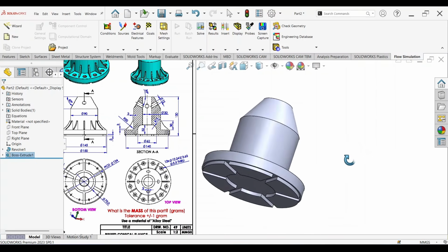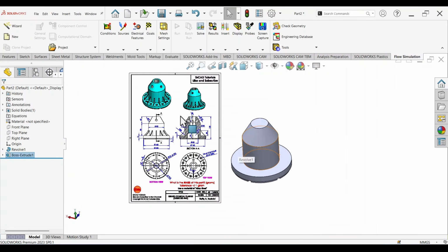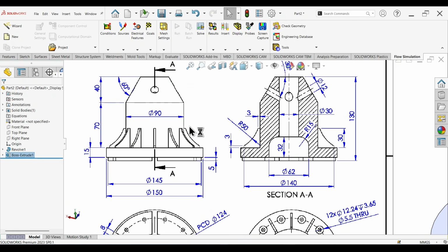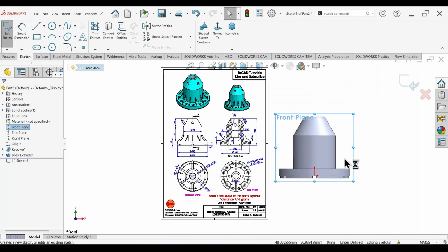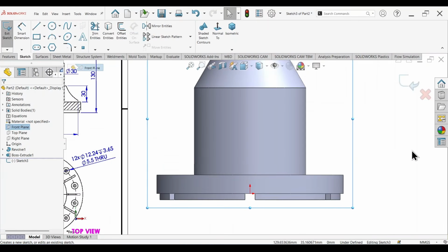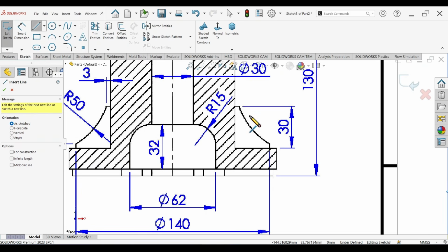All right, so now we completed the bottom section of the component. What we need to do is now work on creating the rib. So select the front plane, sketch, zoom in closely, activate the line tool, and we're going to very simply sketch out this top portion right here of the rib, leaving out the bottom edges, the side edge and the bottom edge for the rib, right?